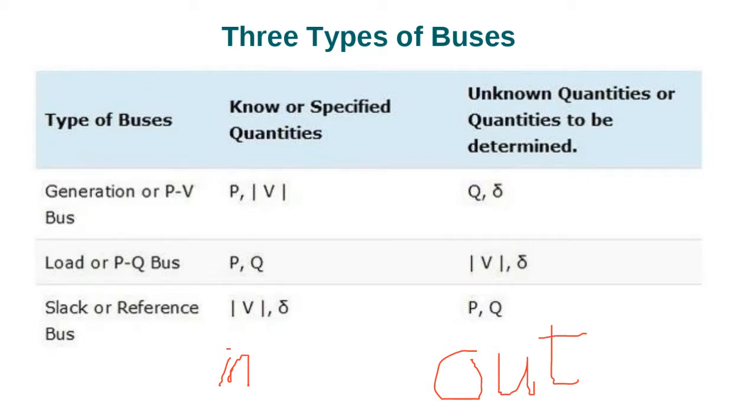Input means that you need to enter the P and Q of all these buses. What's the voltage of the reference bus? What's the angle of the reference bus? Now we usually put this as 0 angle. And then for all the angles here, when you say this is, for example, 0, and this is, for example, -5, what does it mean?